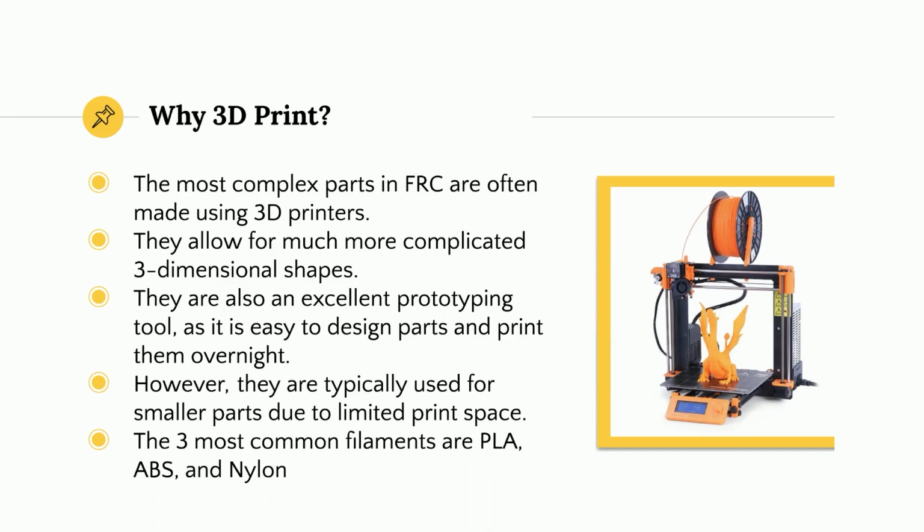They're also an excellent prototyping tool, as it is easy to design parts and print them overnight. If you're using SolidWorks or Fusion 360, it is as easy as just exporting it as an STL file and bringing it to whatever your 3D printing software is. You can bring a part in CAD into a 3D print in less than 5 minutes.